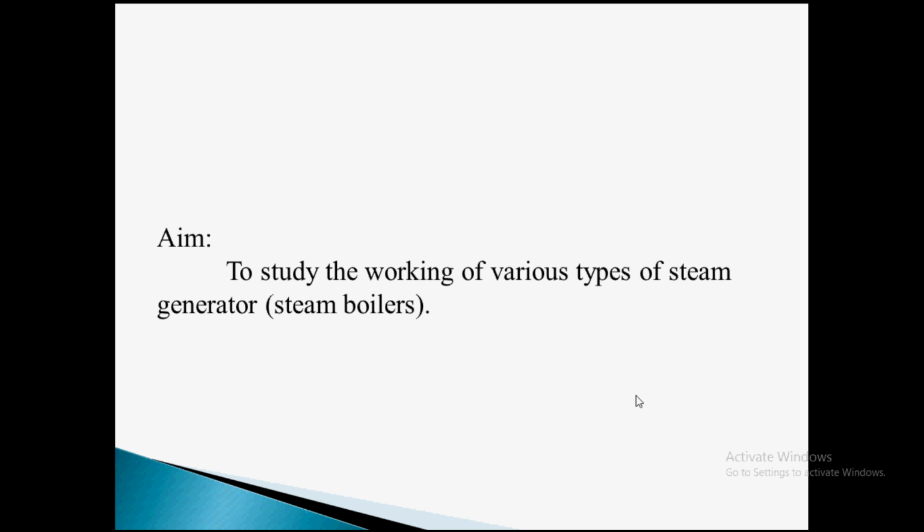So how will you select these steam generators? The selection of type and size of the steam generator depends upon the following factors. First one, what is the power required and working pressure? Second one is the geographical position of powerhouse. Third one is the fuel and water availability, and fourth one is probable load factors.